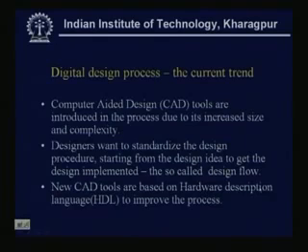tell that tool or software that this is the specification of the circuit, or if we consider the system, then this is the specification of the system, this behavior I want to realize. For that purpose, we use a hardware description language, as its name implies, a language that will tell us that, see, this is a block that represents an AND gate, this represents the flip flop, this is a wire, this is a clock.